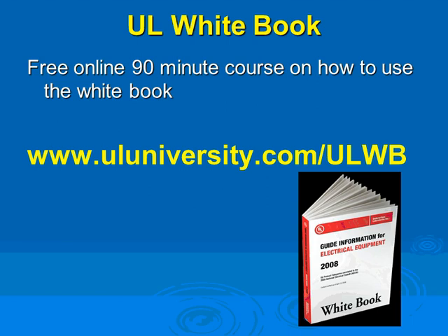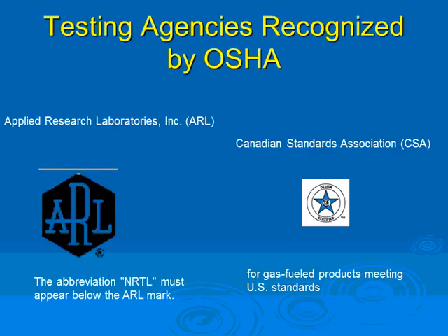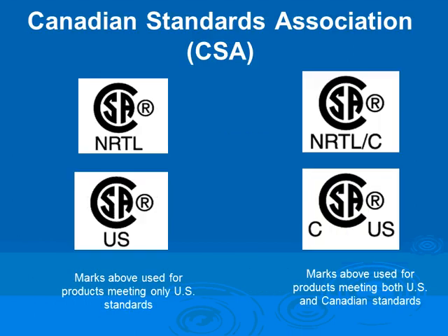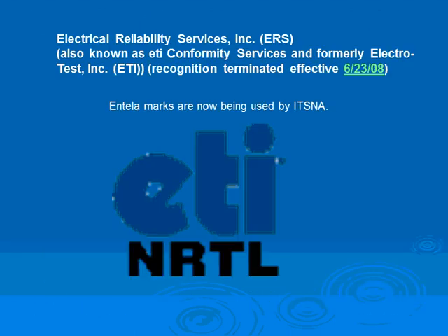If you know the equipment in the NEC code book, that's all you need. I want to know load center, right? From the NEC code book, you can go to the white book and find the UL labeling. Or you can contact UL and they'll give you a lot of information. They're more than happy to help you. So all those guys are acceptable and approved methods of getting into energized equipment.